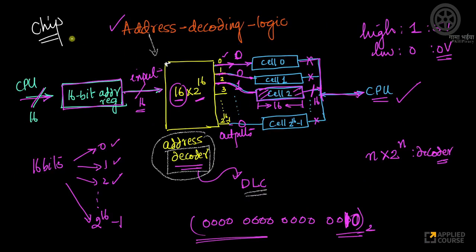Physically, if you look at it, the chip doesn't store addresses, doesn't have addresses anywhere. This is cell 0. It only has the circuitry or the memory locations to actually store these cells. Which cell we choose is done using an address decoder. So the chip itself does not have the addresses physically. Addresses is what we logically imagine it to be there. And all that is physically implemented using an address decoder. So actually there is no specific address anywhere.